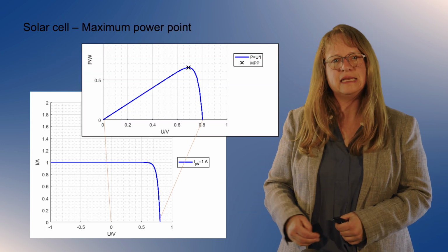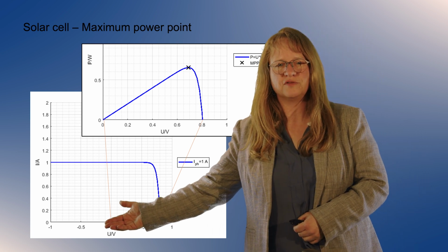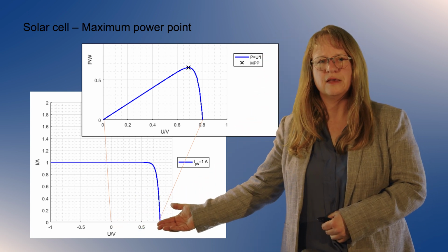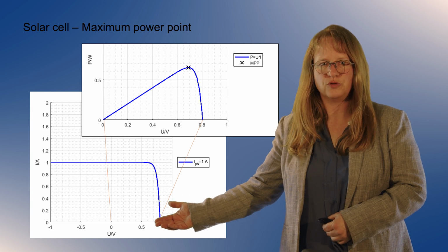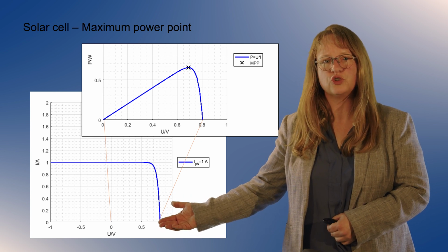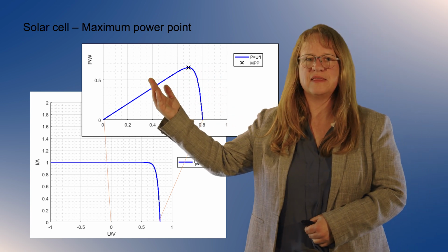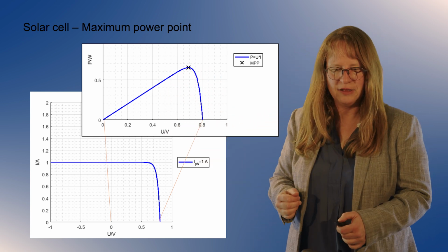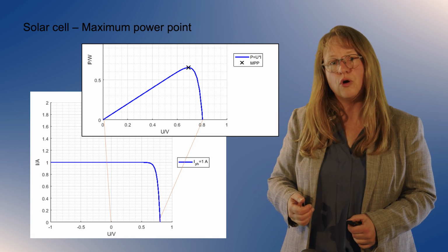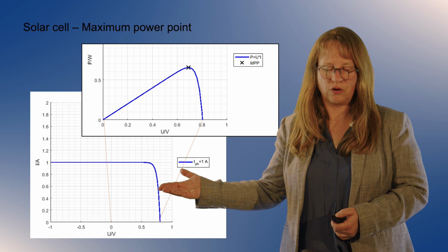And we have seen that we can calculate for the values of 0 volts to this crossing point here to the negative values. This is called the open circuit voltage. We can calculate all of the power values and then define where the maximum power point is. And therefore, we now know what power we can extract for a given IV curve.